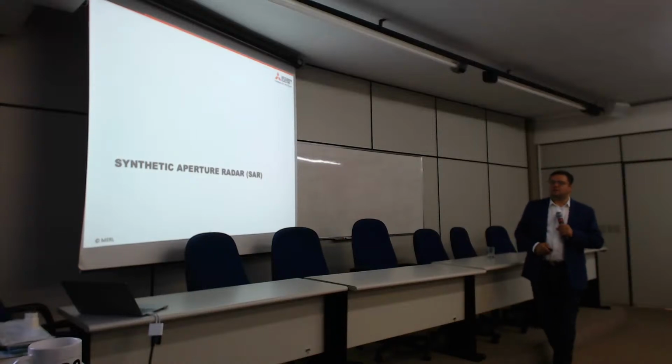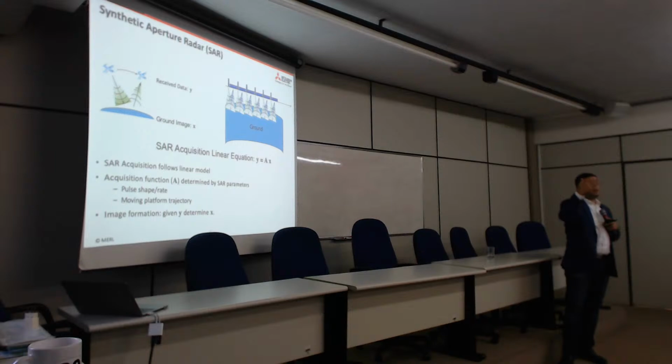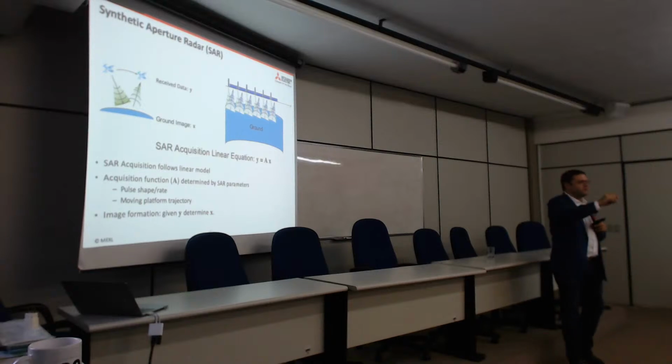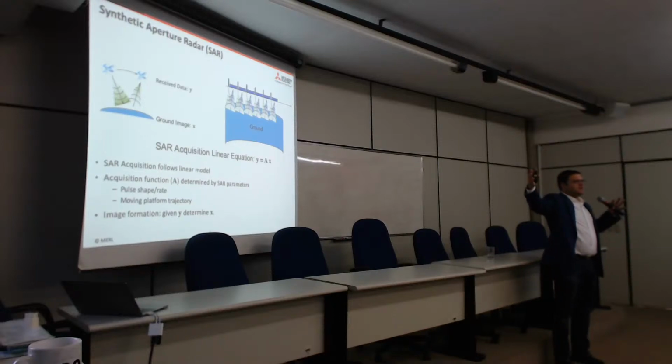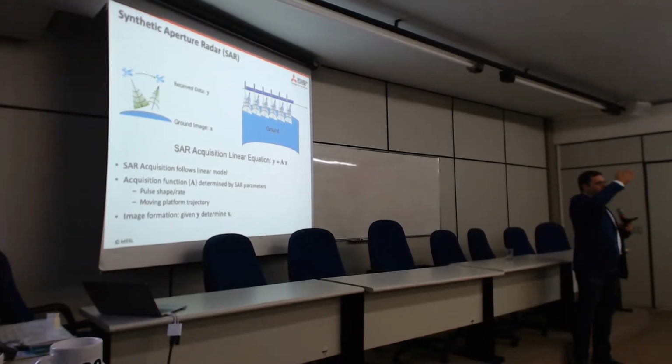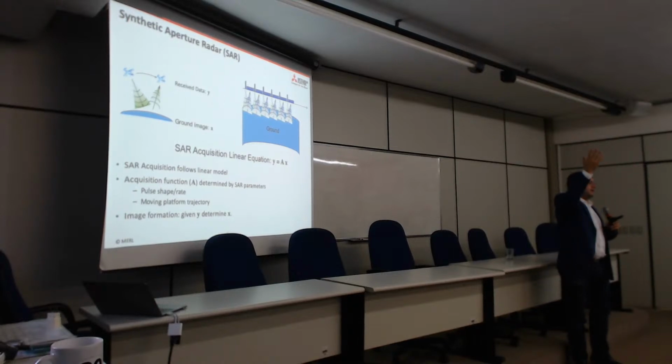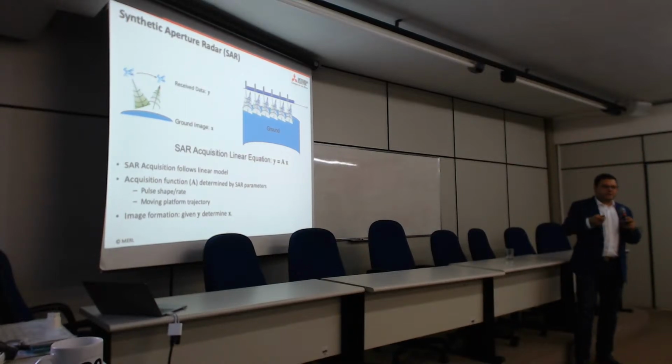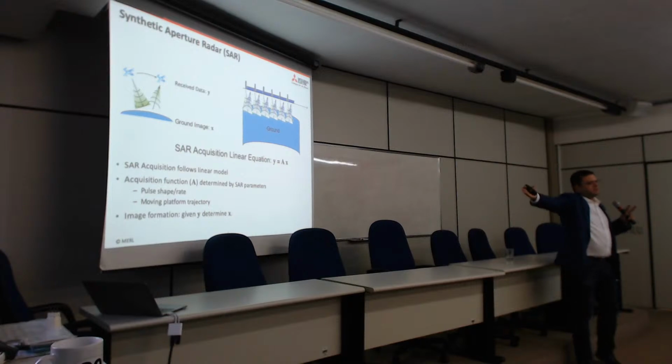Synthetic aperture radar. It's a very interesting concept. Has anybody worked on synthetic aperture radar? Doesn't matter. It's very simple. It's the same idea as panorama with your camera, kind of inverted. As you said, the array aperture, the size of the array, is what tells you a lot about your resolution. So how can we make a big array? We put it on a plane and we fly the plane, and we take snapshots through the path of the plane, or a satellite, for that matter. And this way, the size of the array is basically the track of the plane.